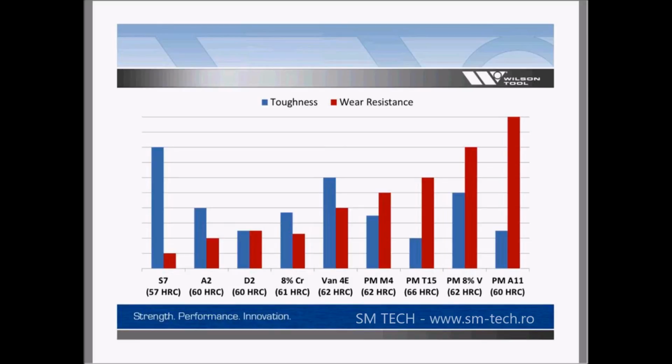You might think you're seeing a wear issue though. Make sure you're not just passing it off as a wear issue. Especially in stainless steel, you see a lot of wear concerns where you think that going to a harder material would be the way to go. So we switch to a 10V, let's say, because that's going to give you more wear resistance. But typically speaking, when you run a stainless steel with a tight application, you're actually getting microchipping. Like we mentioned earlier, the material wants to fatigue and break away on those edges because the tensile strength is just not there. So that toughness comes into play.